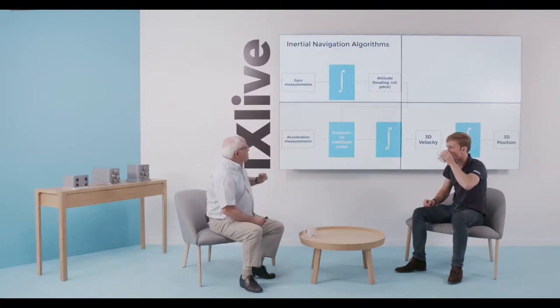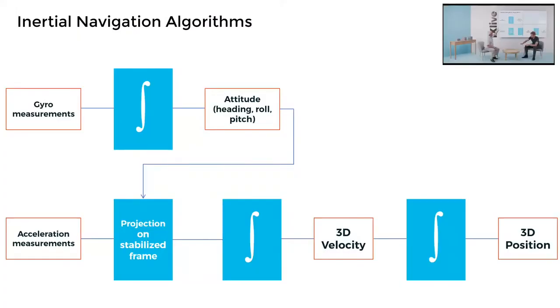From the gyro measurements and acceleration measurements, we have some integrations which will provide, from the gyro, the attitude parameters: heading, roll, and pitch. And from the acceleration, after projection on a stabilized frame, we integrate once to get the velocity and a second time to compute the 3D position.